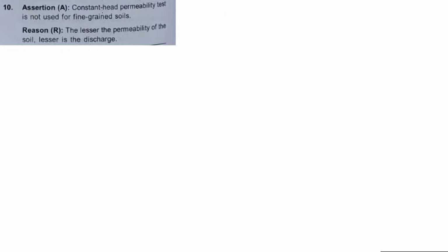The assertion is: constant head permeability test is not used for fine grained soils. For fine grained soils, the falling head test is used, so this statement is correct.